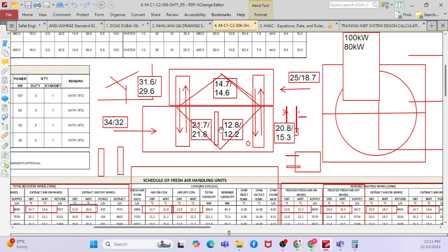For ventilation purpose, I should just replace the existing air. I am going to take out some of the exhaust air and then I have to replace it with fresh air. So when I replace with fresh air, I should match it to the same as the return temperature, right? Yeah.